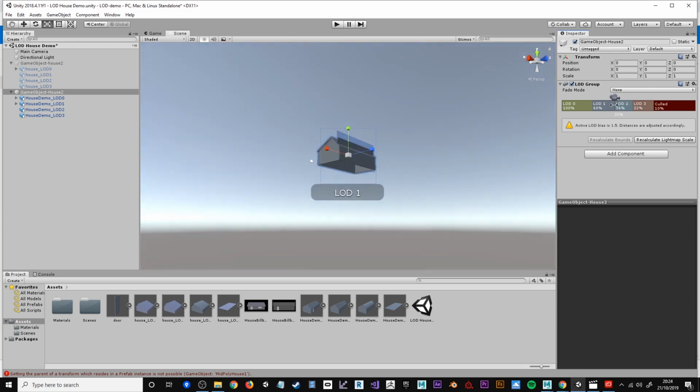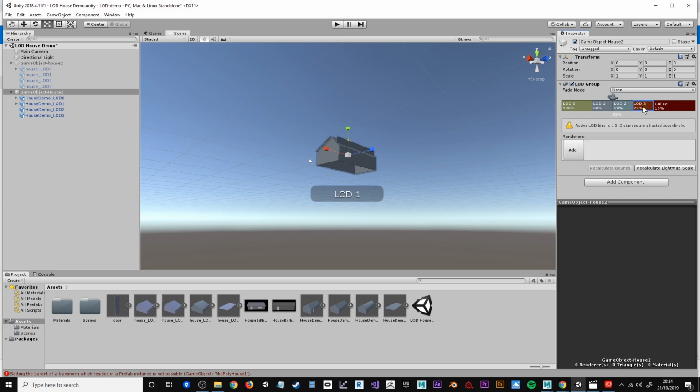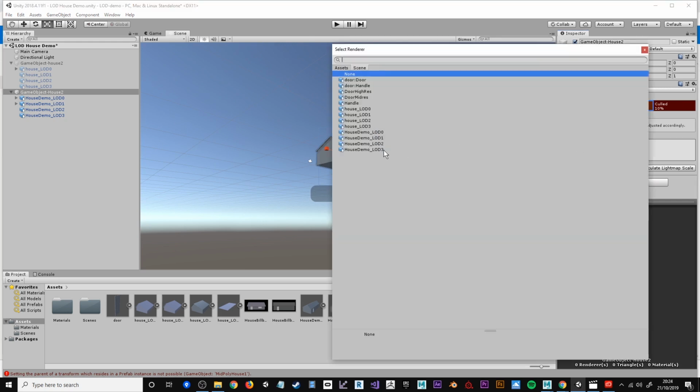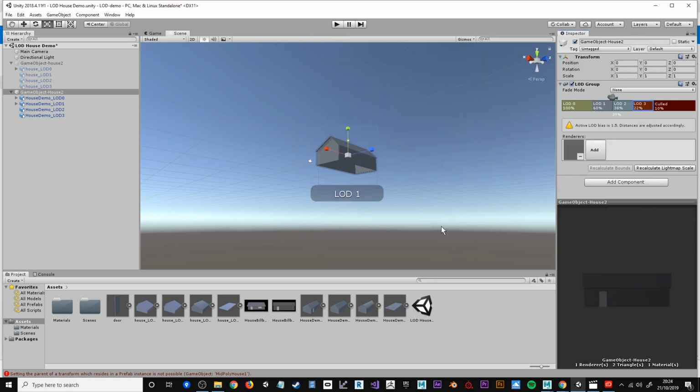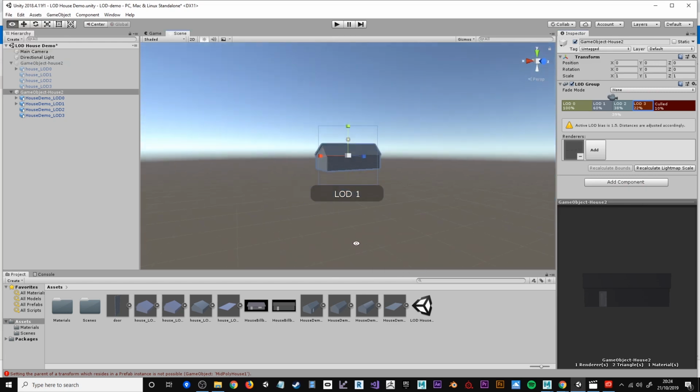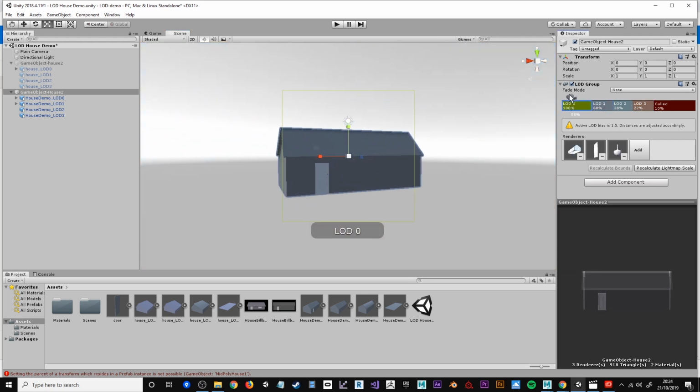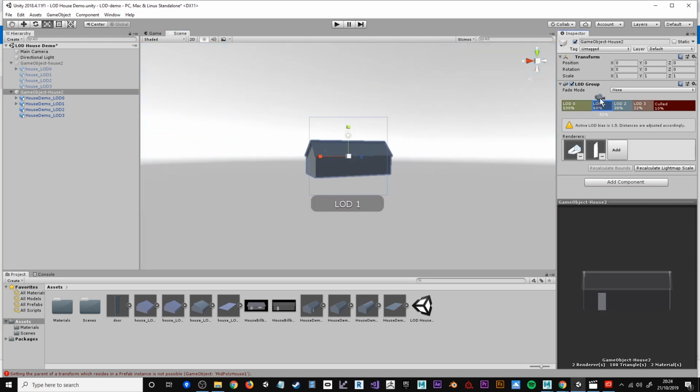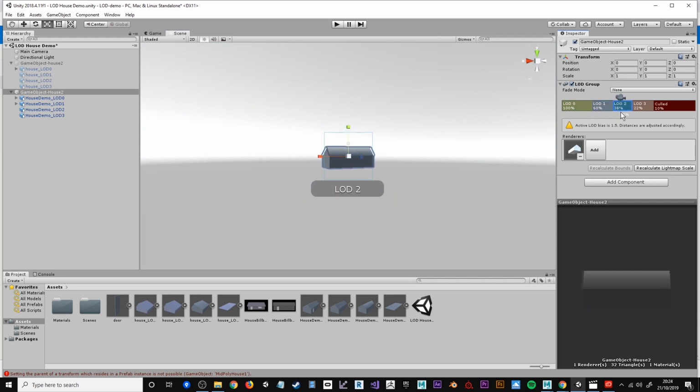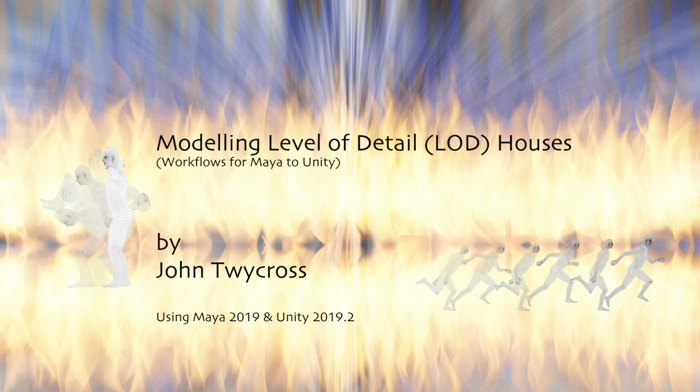And you can set how close to the camera they are when they change. Level of detail 3 just comes in there. And now when we preview that, drag the camera along, and you'll see the detail coming there. An extra edit on that would give you a door on that, but we'll add the textures in afterwards. So that's it, and that will run and optimize your scenes.